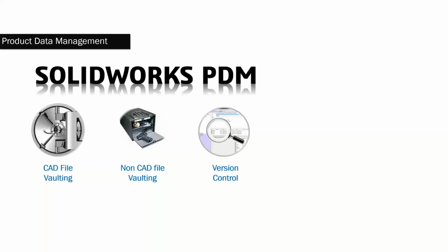As you put those files into the vault, it's going to start to create a version every time you do a check-in and check-out process. You're going to take ownership, make some changes, and put it back in the vault using a check-in. That creates a secondary version. So if I do that every day for a week, I can go back to Monday, Tuesday, Wednesday, all the way through the process and look at what was done each day. That applies to one week, a month, a year, or even several years. You can go back in time, so that's a great way to use PDM.